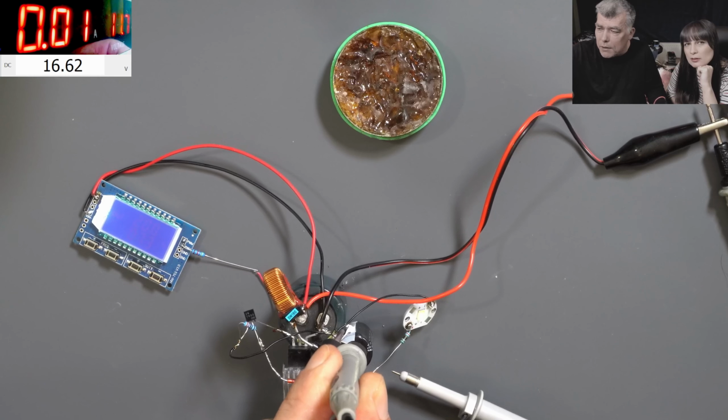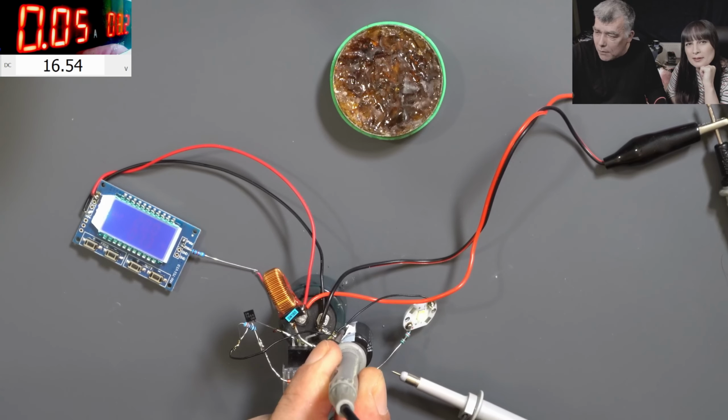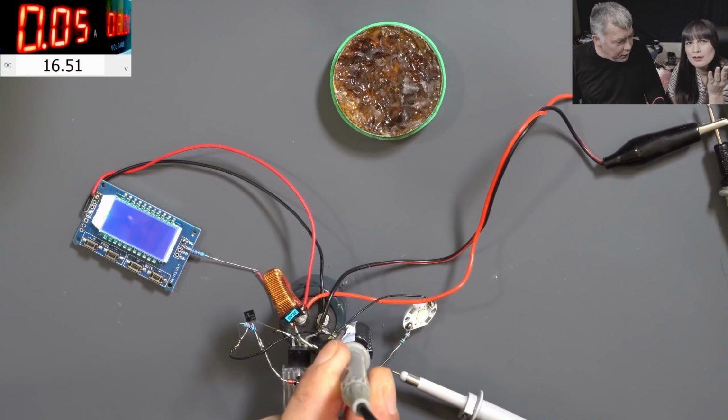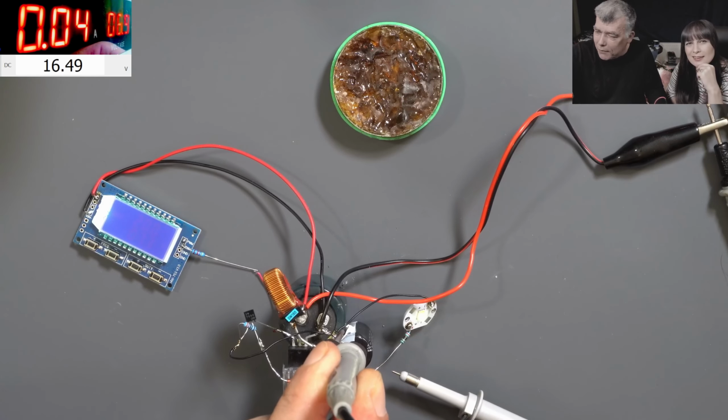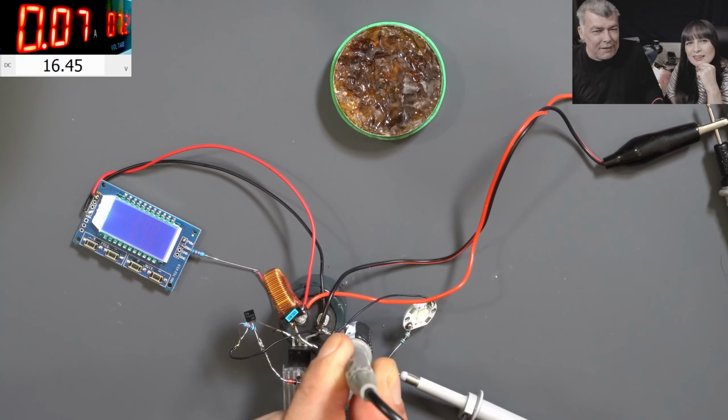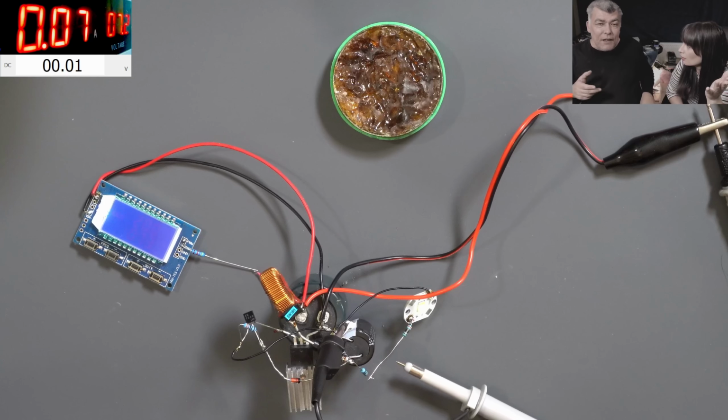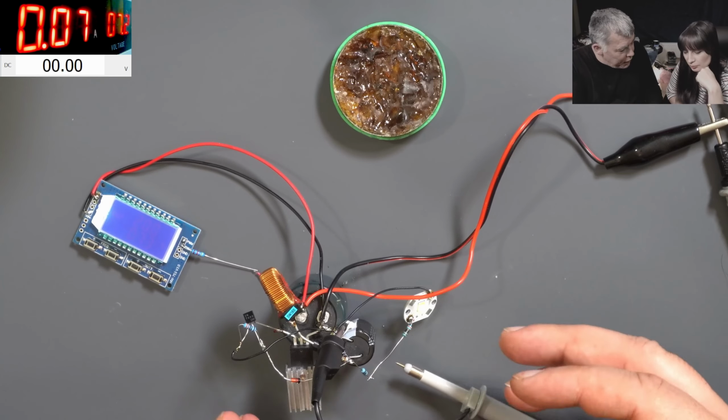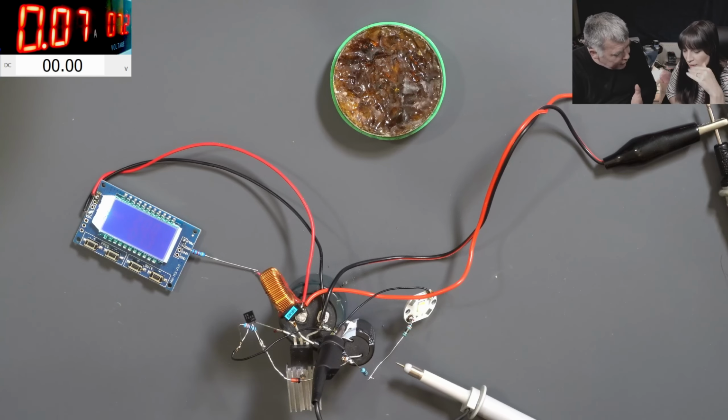Okay, let's go down to 10 volts. How is the output? It's still 16 point something. Let's go down to 8 volts. It's still the same output voltage. Okay, let's go down. Let's see how long. We can go down to 7 volts. So you understand? It's like nearly half. So the circuit is still trying to keep that voltage the same, which is set up by the Zener diode.